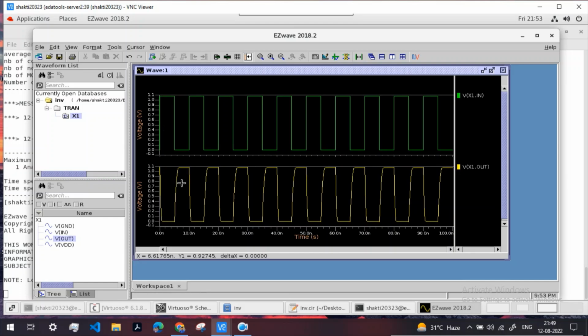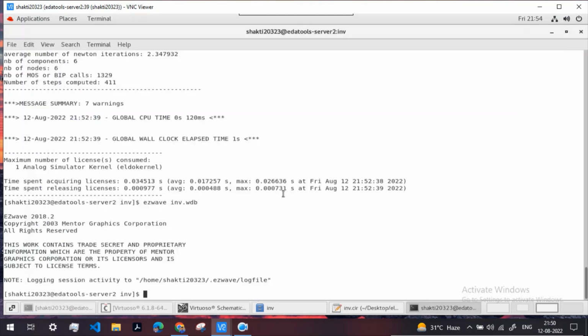So this is the first rising edge, this is the first falling edge, this is the second falling edge. And similarly, this is the first rising edge of the output, this is the second rising edge of the output. And to calculate the propagation delay, suppose we are calculating the rise propagation delay, you can see that we are calculating it at the first rise of output, and here the input was falling. So the distance from this 50% of input to this 50% of output when it is rising is termed as rise delay. So this was all about plotting the transient simulations on ELDO.